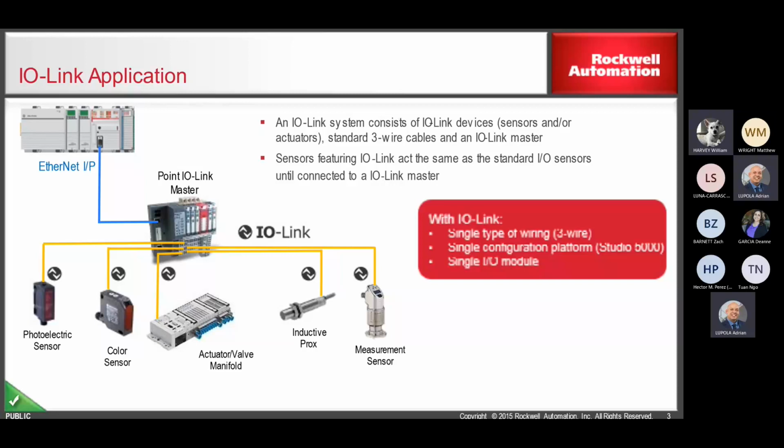Every sensor manufacturer and valve manufacturer out there makes stuff. But when you see that little symbol, the little up and down carets with IO-Link, I get a lot of data. So over 4 wires, I have to go through what's called an IO-Link master. This is a Point IO version. It's in-cabinet. There's also an ArmorBlock on-machine version. You'll see it in another slide.